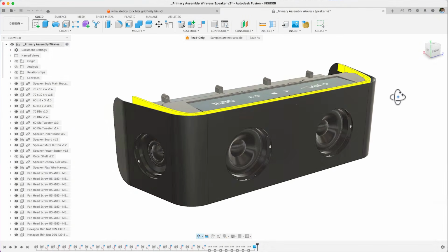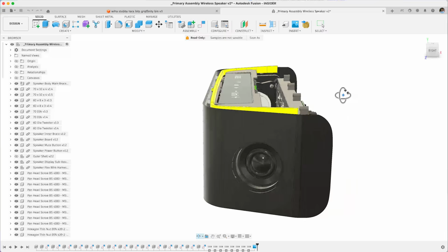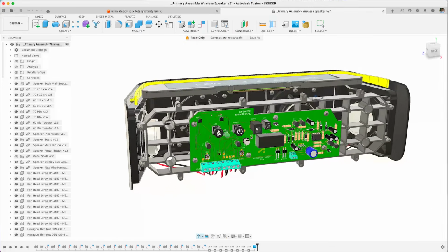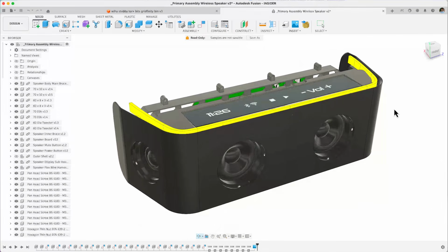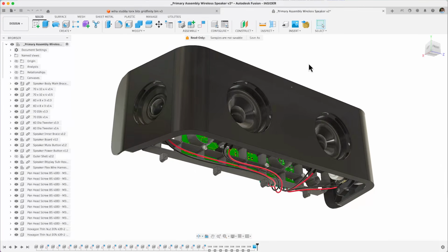This is one of my favorite tips in Fusion. It's one of those things where if you know how it works, it's really useful. And it all has to do with keyboard shortcuts and camera focal lengths. Let's check it out. So when you're looking at models in the design workspace, your camera focal length is set to 90 millimeters. But sometimes you want to go a bit wider.